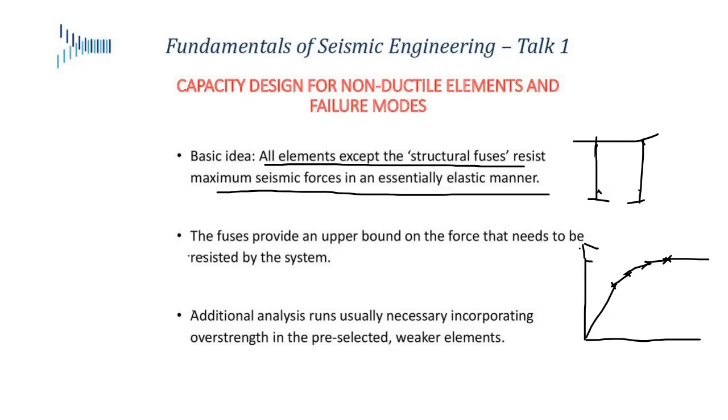Now, I cannot have more force in the system than this. I design the cap beam and the columns outside of the plastic hinges, my foundations, everything else is designed such that it stays elastic. So the only plasticity that's happening in the system is basically concentrated within these fuses. So when a larger earthquake comes along, this force is unable to grow. It's unable to go beyond this point. The only thing that happens, as I was describing before, was the displacement increases.